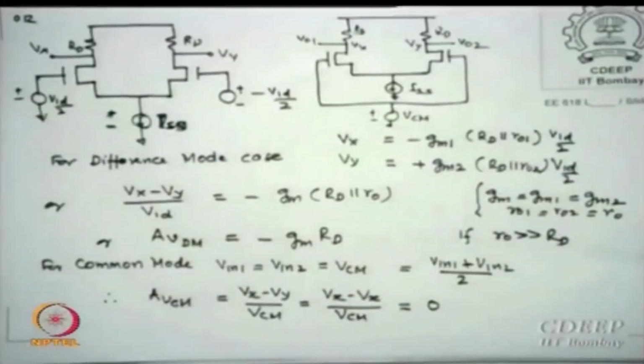This is essentially the main feature of a differential amplifier. The assumption in all this, and I repeatedly say why this cancellation is important, is that in real life one believes these two transistors will not be too far apart. They may be two input signal lines, or sometimes one ground and one other line, in which case the noise may not be put separately at different places. So the assumption is that if noise sits on this, the same noise will sit on that, and if that happens the common mode noise will actually get rejected. That is the feature these diffamps provide.